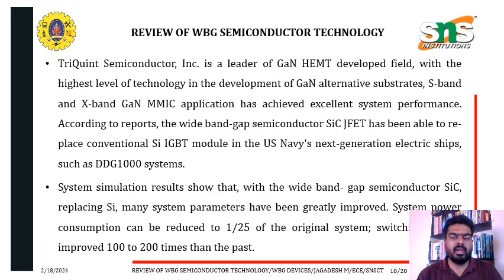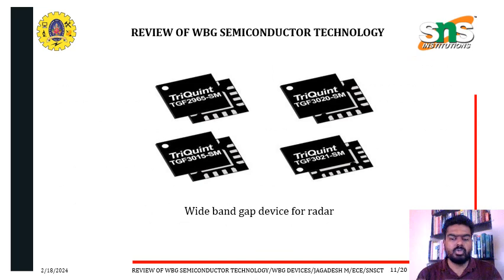TriQuint Semiconductor is the leader in the gallium nitride HEMT field, with the highest level of technology in the development of gallium nitride alternative substrates. S-band and X-band GaN MMIC applications have achieved excellent system performance. System simulation results show that with the wide bandgap semiconductor SiC replacing Si, many system parameters have been greatly improved. Wide bandgap devices for radar application are shown in this diagram.